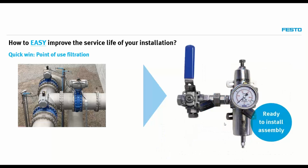Instead of having individual parts, this is, for example, a solution we provide as Festo. It's a turnkey design with the filter regulator, pressure filter bowl with a 40 or 5 micron filter, and a manual on-off valve, where the pressure on the side of the filter regulator can always be vented into this silencer. So this is one of the options we can do, and it's easy to install, and it protects the service life. This investment is negligible compared to the cost of actuators and the performance it has on the butterfly valves in this event.